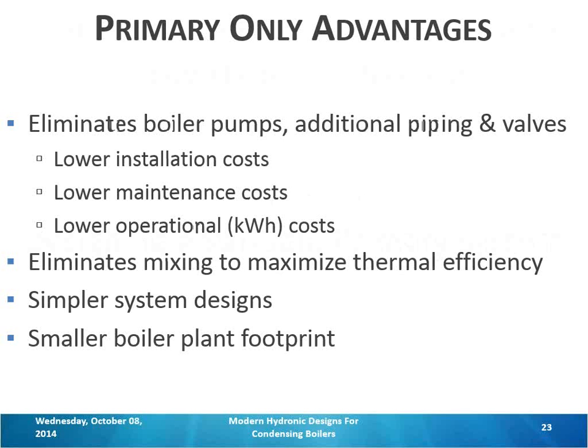On our design day, this building has a 3.6 million BTU an hour load. And then on our mild day, so our spring or fall day right before our warm weather shutdown temperature, we have a 400,000 BTU an hour minimum load. We're designing the hydronic system for a 30-degree Fahrenheit differential temperature.